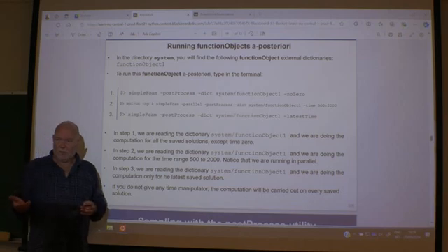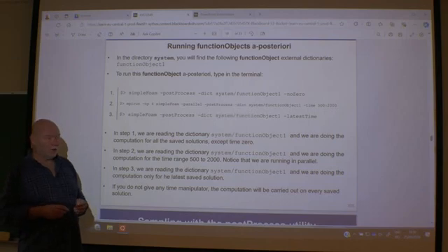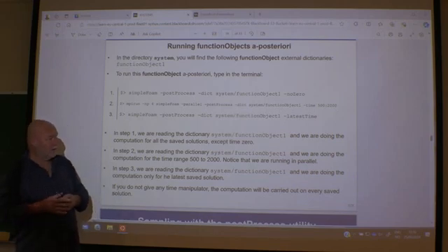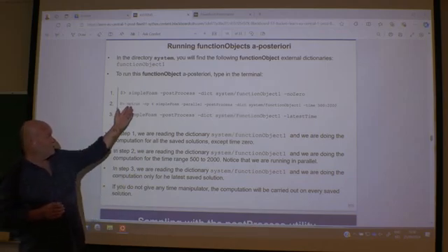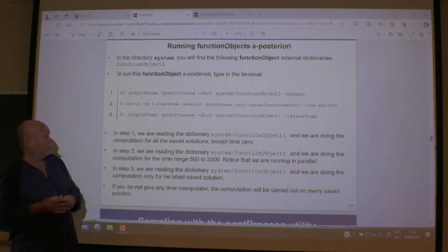You get one folder for processor number 0, and then another folder for processor number 1, and so on. And inside those folders, you will find your time result folders. But they will just be part of the entire domain. Hence, you have to look into all of them if you want to, say, execute such a function.